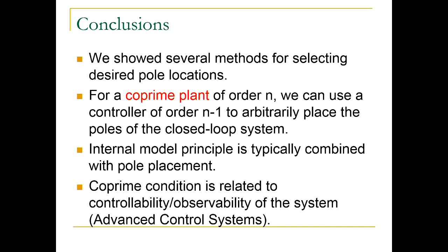Controllability is basically a property that says you are able to control your system. So if you have a car and I take out the steering wheel, the car is not controllable. Observability is related to whether I can figure out internal states in the system from measurements. So if I don't measure anything, if I'm a blind person, I can't really see. The system is not observable. There are no sensors, the system is not observable. There are no actuators, the system is not controllable.